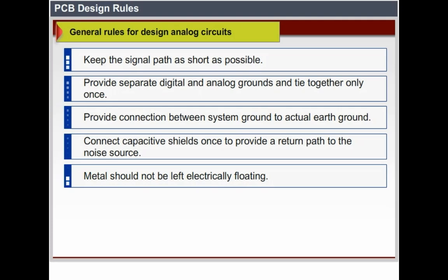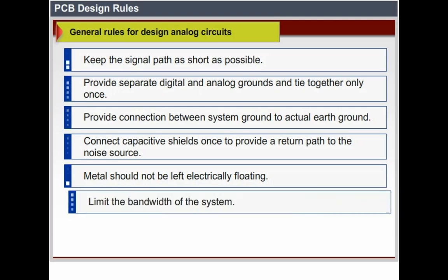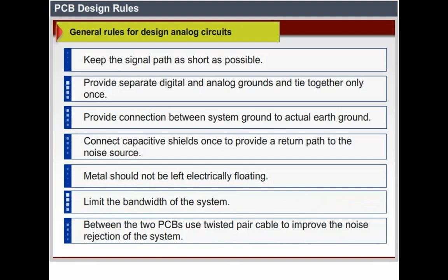Metal should not be left electrically floating. Limit the bandwidth of the system. Between two PCBs, use twisted pair cable to improve the noise rejection of the system.